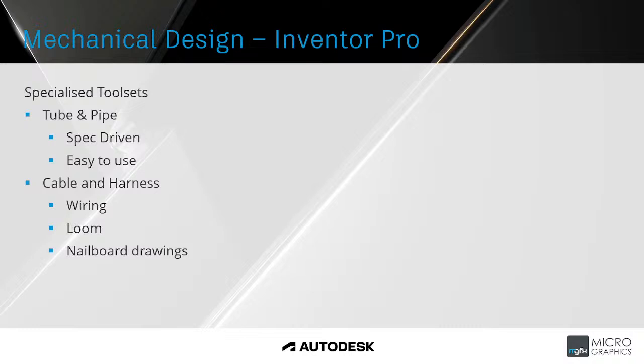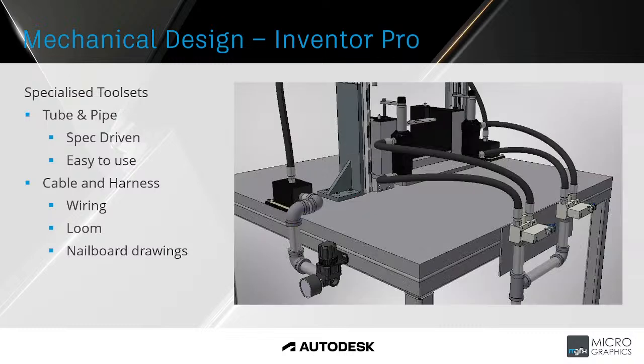So those are not the only tool sets. We can also move into piping and cable and harness. So within the assemblies, we can also go into the tube and pipe environment. And this allows you to create spec-driven tube or pipe runs. The example on the right here is a mixture of solid pipe runs where we have threaded fittings and elbows. And then we also have our flexible hydraulic line, which would have had crimped fittings on the ends.